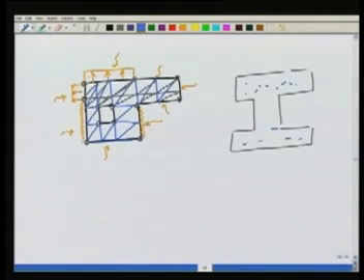So these material boundaries also have to be clearly honored when we are talking of making the mesh. These nodes, in fact, demarcating these material boundaries have to be also put, and we also have the other ones corresponding to geometry, and then depending on the boundary condition, for example, here I may have a traction applied or a flux condition.